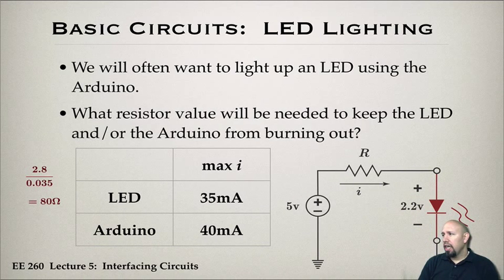Okay, so it turns out that even though this can handle 35 milliamps, you don't want it. That's the maximum. That really is the maximum, and you really only want to use that for a very short amount of time. If you use that maximum for any length of time, it will also fry. So it'll heat up and it'll fry. So you don't ever want to push the device, and you can have the device go up to its maximum, but you don't want to keep it at its maximum, generally speaking.